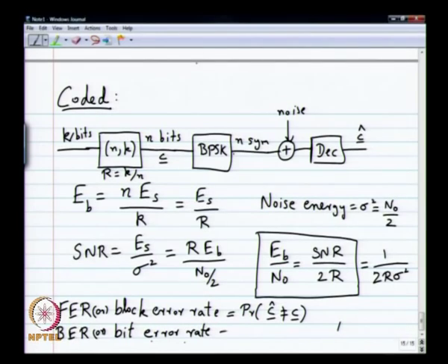So, bit error rate is the probability that, let us say, Ci hat is not equal to Ci. Usually irrespective of i, for most codes this will be roughly the same, and in case it is different for each i, you have to take the average of all of that. So, that is the understanding, but I will write it simply as Ci hat not equal to Ci. It is very unlikely that you get much lower probability, actually maybe it can happen, but usually it is the average bit probability of error. Okay. So, now how do you simulate this?